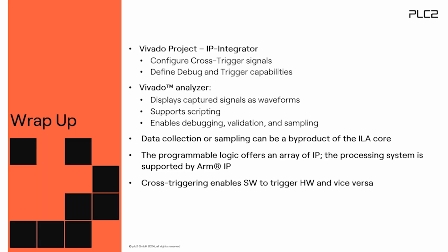And this change is quite fast in the environment of the Vitis IDE, because this is software controlled. But if we need other hardware signals, other probes, obviously, a rerun of the Vivado design is necessary. So this takes a bit more compilation time, obviously, but gives us the capability for each signal at the end. So therefore, you can have really well-adapted debug sessions for more complex challenges.